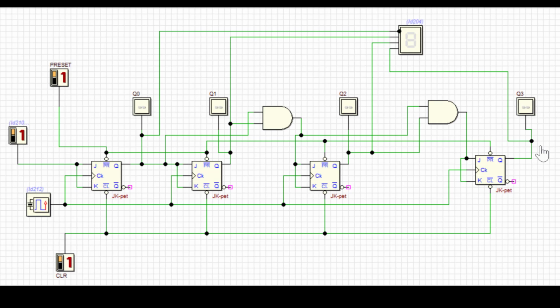You can do this at your own time, how to get this expression for the fourth flip-flop, because till 1, 2, 3 we already did it, so you can take it for granted. The fourth one you have to do manually. For the time being we assume it is already derived. The fourth flip-flop input should be Q0, Q1 into Q3.